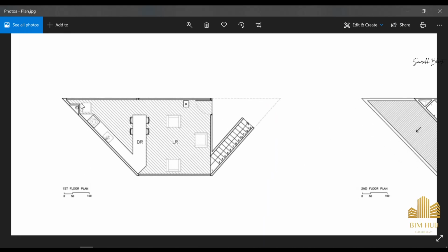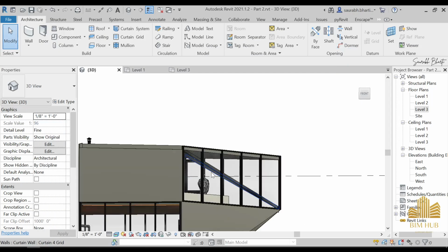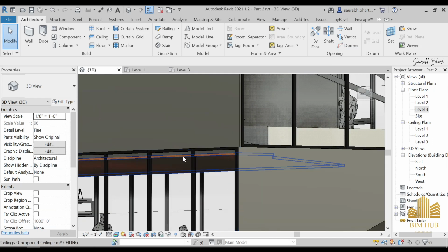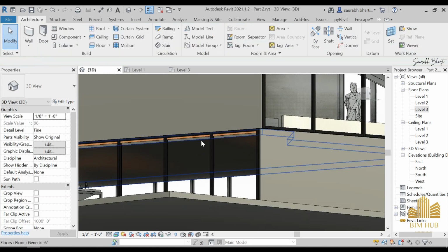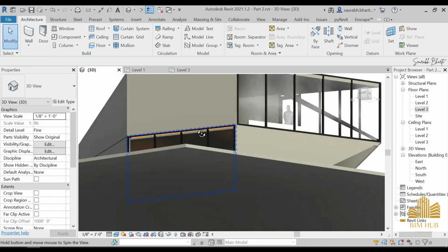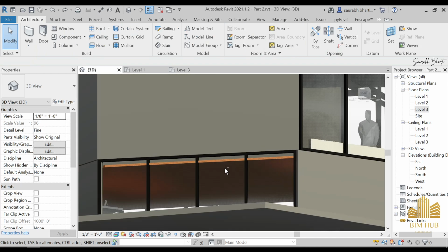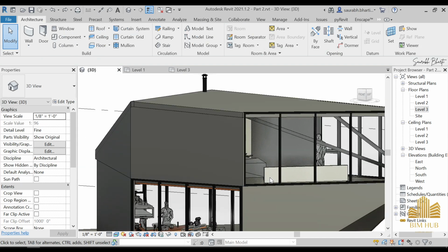So we have completed almost everything except this ceiling on the top portion. And if you want to increase the size of the ceiling, for example, this is at 9 feet 4 inches, you can keep it at 9 feet 8 inches, so that it is just visible a little bit outside. And now it is fine. And let me see. Okay, we have to keep it the way it was, because we have our work floor at this place, so we will keep it.